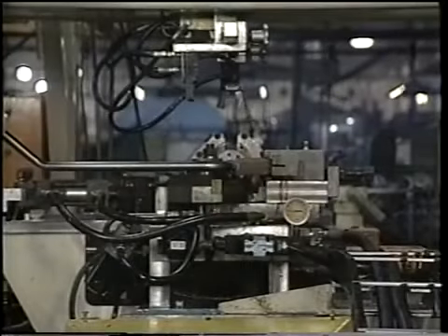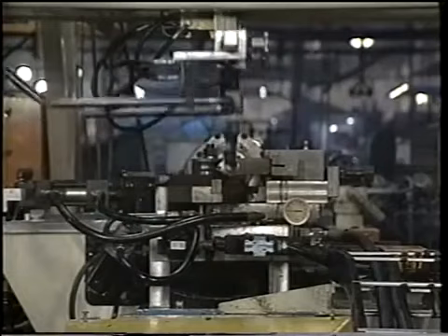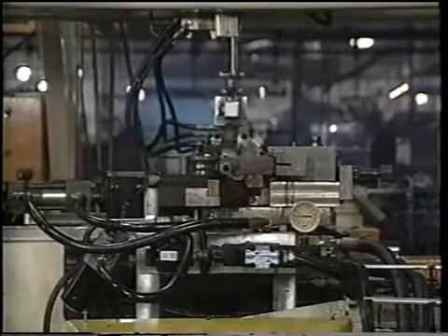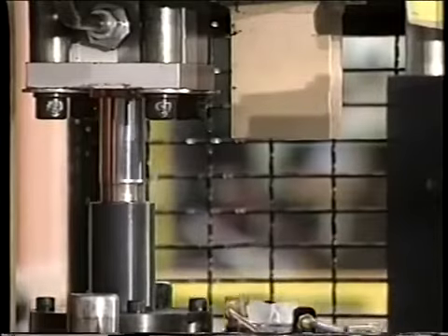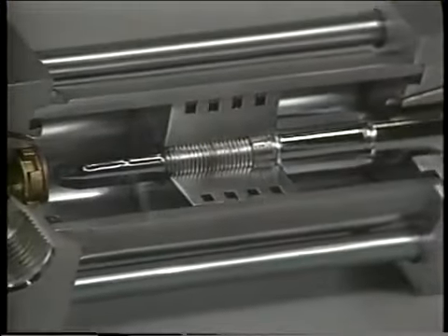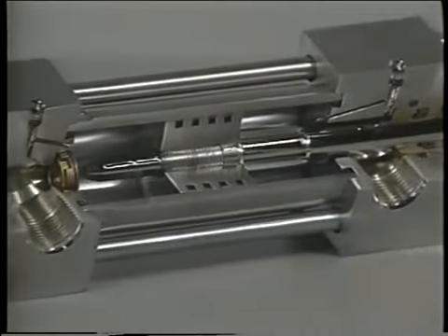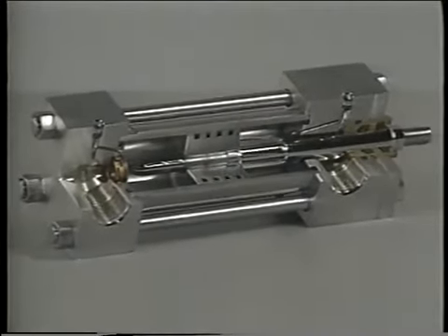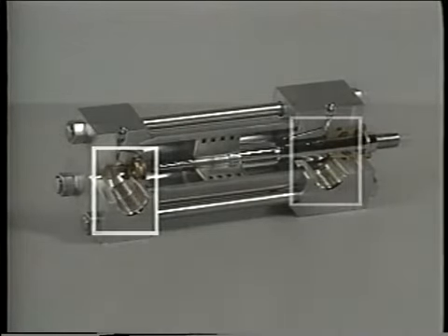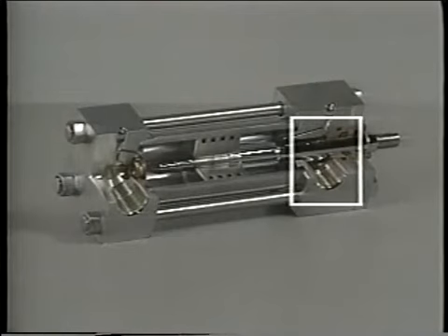In hydraulic systems, actuators convert the flow of pressurized liquid into mechanical energy and motion. This motion can be in a straight line or linear, like this cylinder. In a cylinder, a piston moves along the length of the cylinder body, pushing the piston rod against the load. One end of the cylinder has an inlet port for fluid to enter under pressure. The other end is vented.